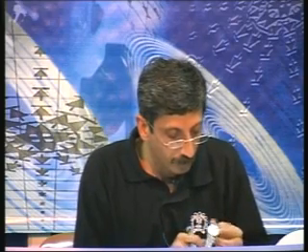3 of them are independent. The rest are all related by these 6 equations. Fine. So why do we use these 9 elements to represent the orientation? The answer is that it is convenient for doing the transformations. These transformations are things that we would like to do later. But keeping that convenience aside, can we have 3 variables which will give you orientation uniquely without any ambiguity?